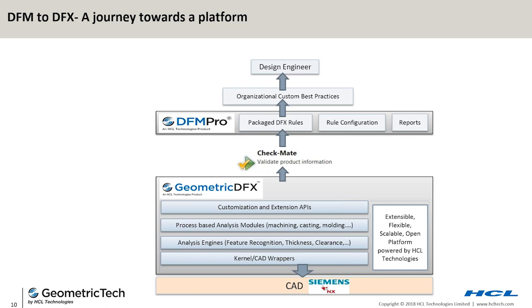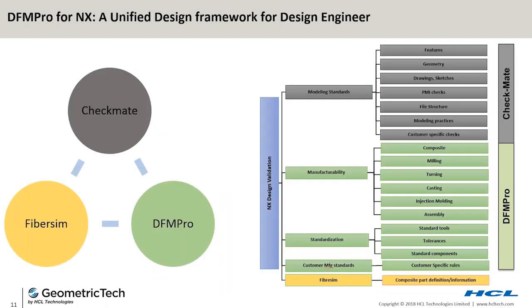It consists of process-based analysis modules such as machining, which is milling, casting, molding, then turning, additive manufacturing, and so on. The backbone of these is the feature recognition and thickness engines, which validate certain critical areas of your design and help you bring out a rule framework which can be configured and tailored to specific requirements.